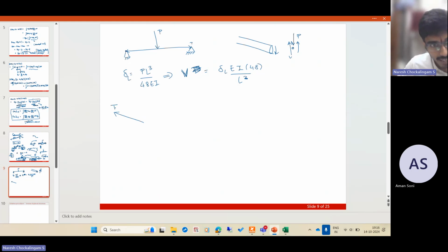But when you have a tension, the tension is at some angle. This angle, roughly I can put it as some delta by L, when the deflections are small. And at this point, I'm also having an applied downward force of P. And this is symmetric, so on the other side you have T. Horizontal forces are all balanced.